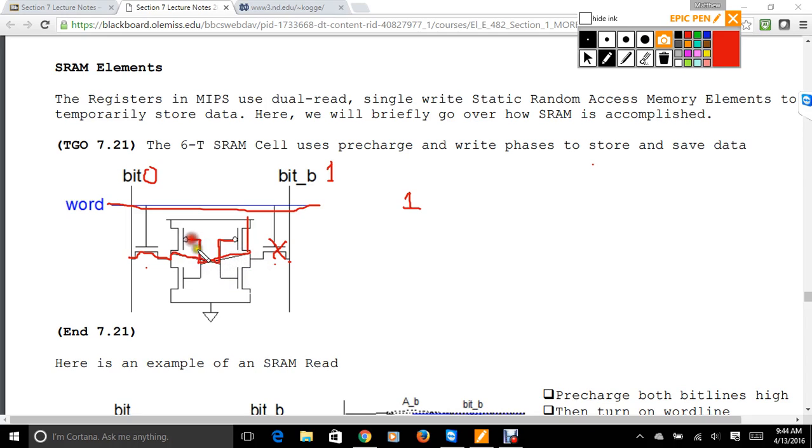This one puts those here. So now it's going to activate this NMOS transistor and allow the 0 to continue. So it's going to strengthen this 0 here, and it's going to keep looping. So that is how we use sequential logic to maintain memory. Every time it goes through, it eventually reaches equilibrium, but that allows it to have a strengthened memory cell.